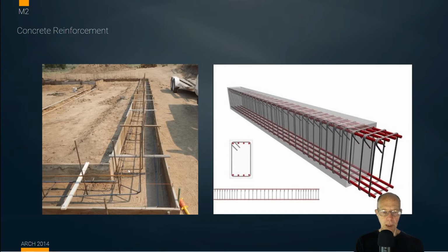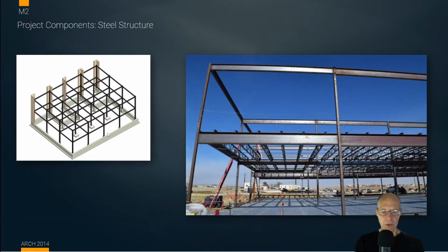Here's a cruder look at a footer. Footers don't have to be precise because they're just creating the starting pad for the wall. It's important that the wall's aligned, but the footers can have a little bit of jogging or whatever with it. Moving on to steel.